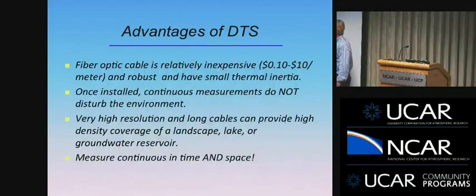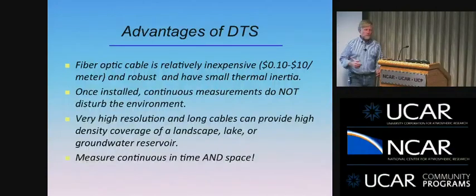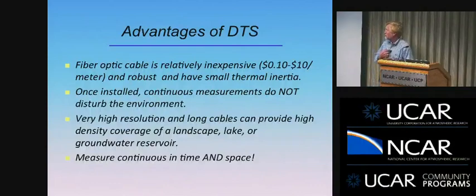Okay, nice thing about it, they can be quite small. We can actually just use almost bare fiber out in the field, so small thermal inertia. Think of a fine wire thermocouple. Once we put something out there, it doesn't move. Okay, it just sits in the environment so we don't disturb the environment. We can get high resolution measurements in time and in space. Okay? For those of us in the hydrology world, we're interested in high resolution space and time measurements.